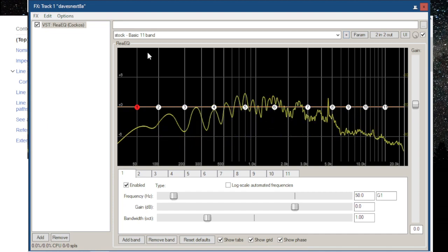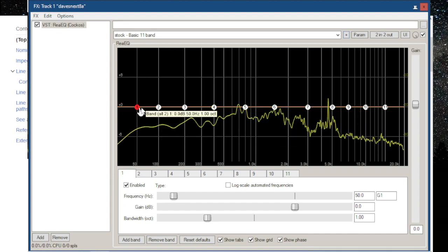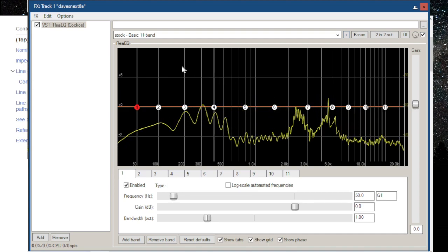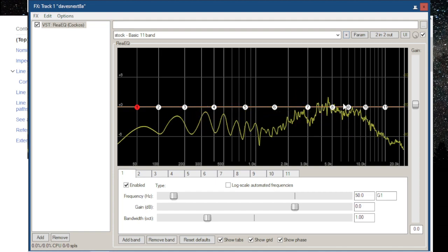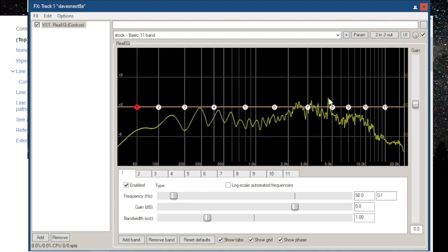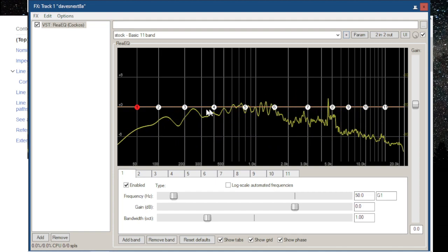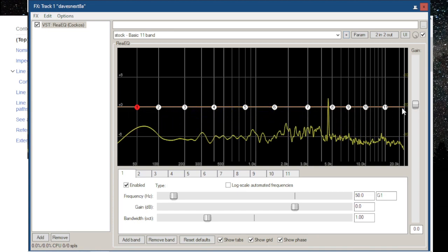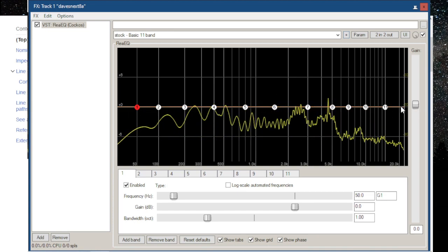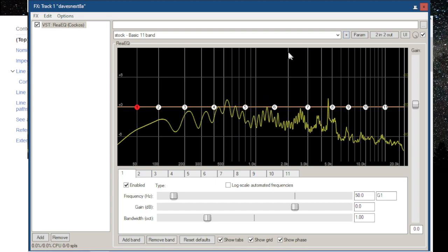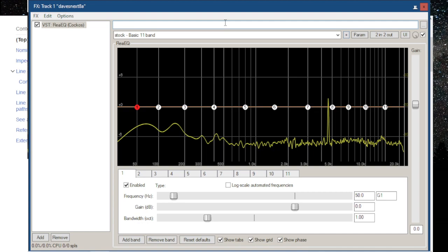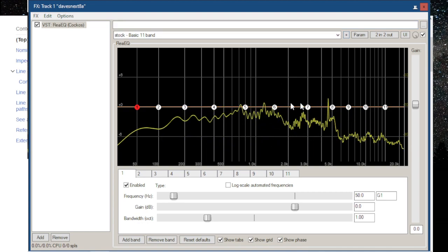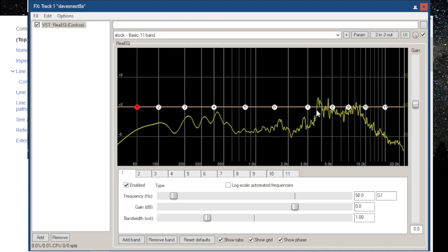Okay, that's a flat response because it's flat all the way across the 0 dB line. So what we want to do is, when we change this frequency, we want to make sure that the level does not change across the band. And that will tell me the responsiveness of my audio, my sound card, and all that. So we can actually turn the level down. This is saying that level is 0 dB.